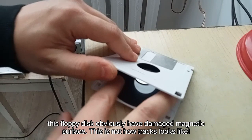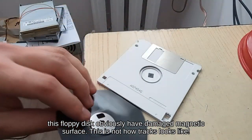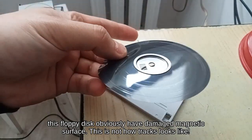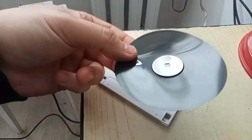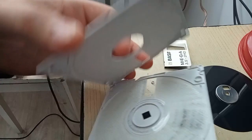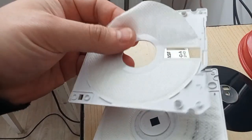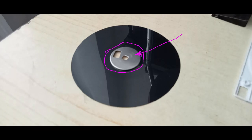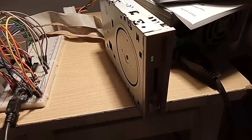Inside the plastic housing, there is a plastic disc coated with cobalt-doped iron oxide material. This magnetic material allows storing digital data in the form of magnetic domains. A polyester sheet reduces friction while the disk is spinning and cleans the disk from dust. A hub is attached to the disk that allows the motor to engage and spin the disk.